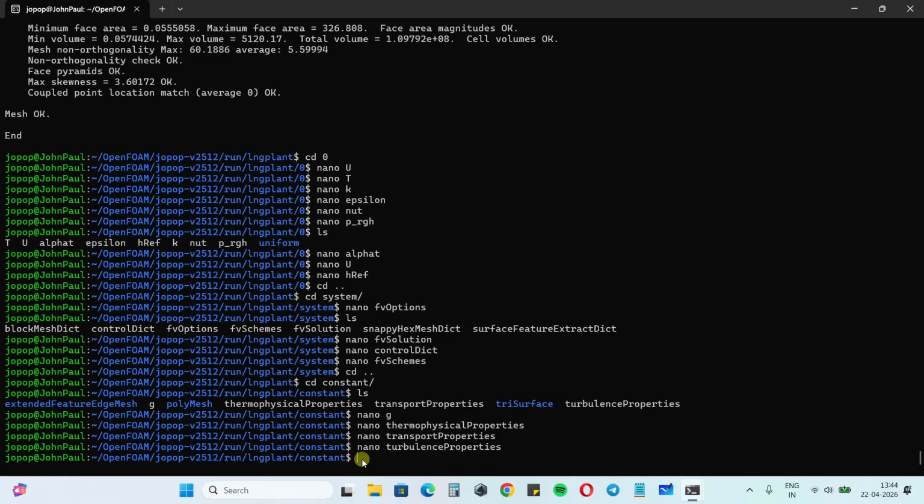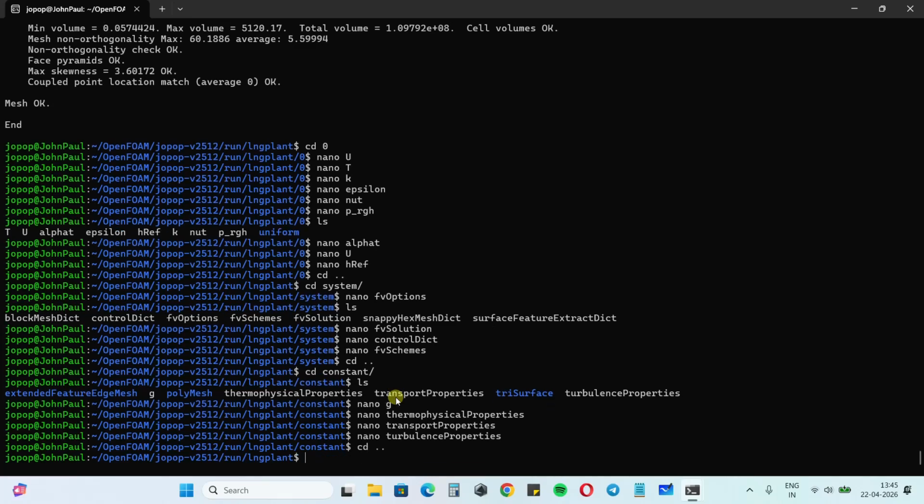So I think now we have covered everything. So we walked through the boundary conditions files, then we set the permeability options, then we modified the solver settings, the numerical schemes, and also all the relevant thermophysical and transport properties that we want to have to solve. Okay, so everything is set. Now we can actually run the solver. So for that we type in buoyantBoussinesqSimpleFoam. Did I get it right?